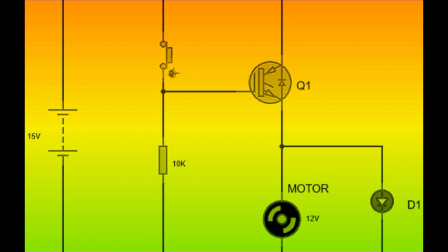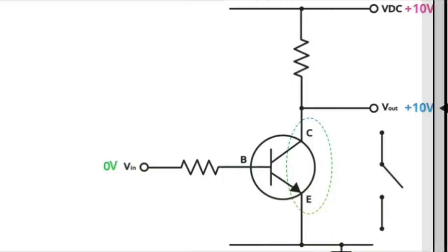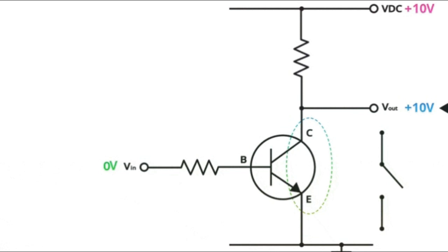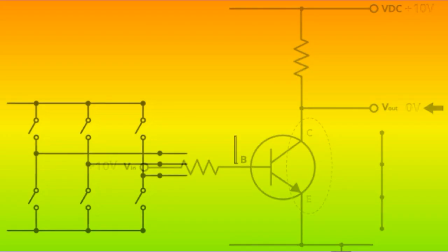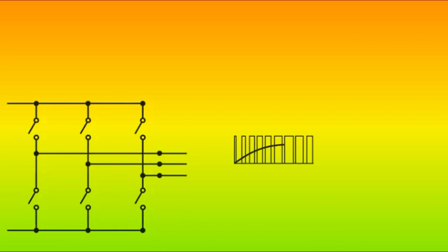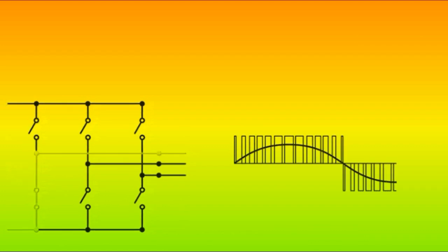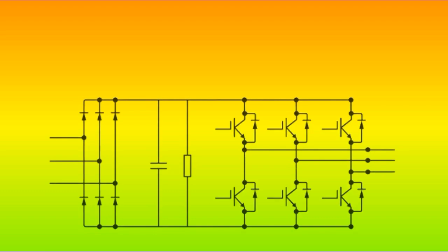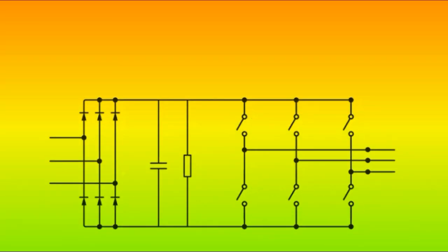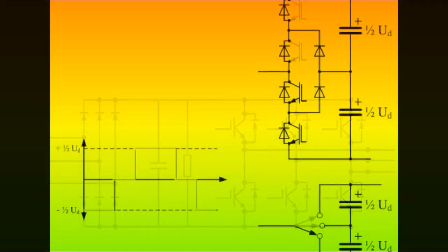Similar to most MOSFETs and BJTs, the IGBT is turned on by applying a positive input voltage signal to both the gate and emitter terminals. When the gate signal becomes 0 or slightly negative, the IGBT turns off. Another advantage of the IGBT is that the channel resistance in conduction mode is lower than that of the standard MOSFET.